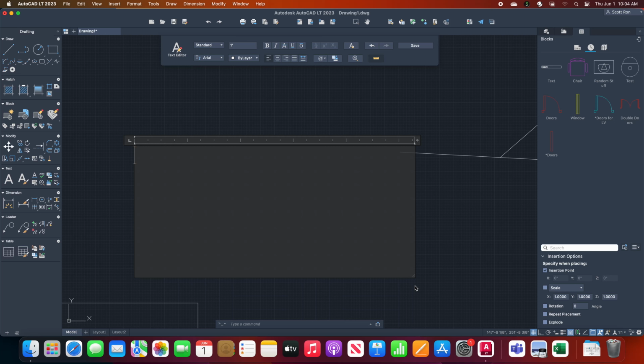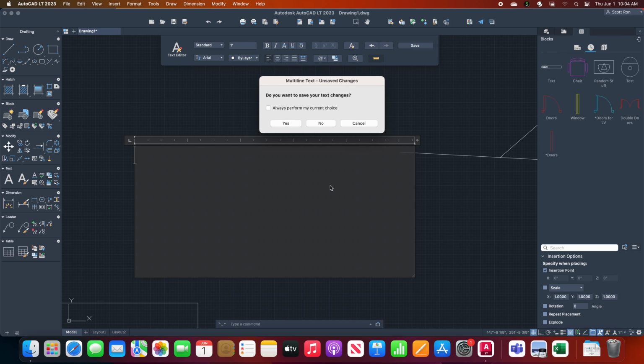Okay. And it's better to have a layer for your text. Always a layer if you have multiple texts. Let's say you have texts for dimensions, you have texts for notations like what kind of ports these are. If you have texts for area, square footage, everything should be on its own layer. Trust me. In the long run, once everything is there, once you see a full-fledged drawing, especially if the goal is a drawing, there's only one drawing that has everything in it.